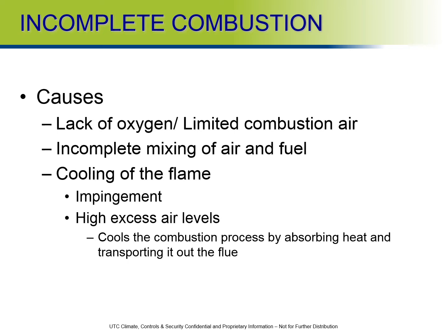So after talking about carbon monoxide and its effects on the human body, what are some of the causes of incomplete combustion? All right, these causes are lack of oxygen, limited combustion air, incomplete mixing of air and fuel, and I'll stop right there because I want to pause and discuss LP kits.